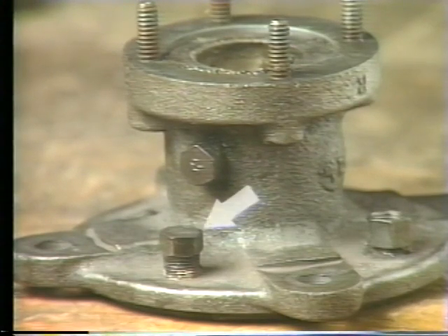You may also notice another plug on the top end cap of the cylinder. Sometimes, between overhaul periods, the piston leathers can stick to the cylinder walls, causing a jerky operation. If this happens, this plug can be removed so that a recommended lubricant can be sprayed around the inside of the cylinder walls. Check your plant maintenance procedures to determine when routine lubrication is done on specific actuators in your plant.